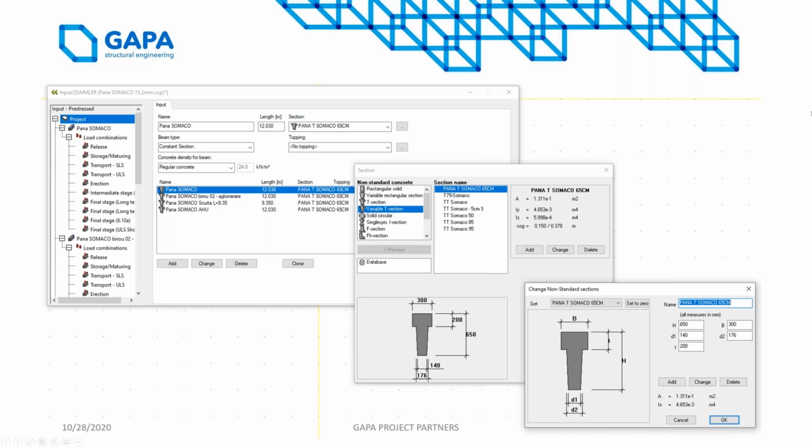So, as you can see from these snaps, it's possible to model several sections in one Prestress file. So for example, in this file, we had all the purlins on this project. We had the typical cases with snow drifts, with higher snow loads, and some other sections that supported some air handling units, which had some concentrated loads.